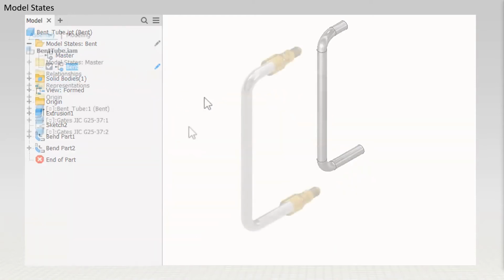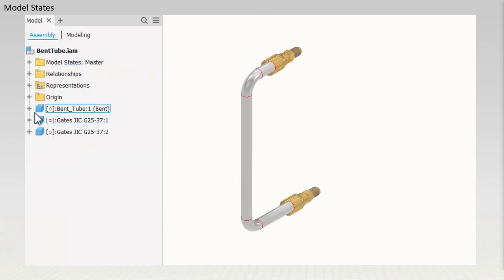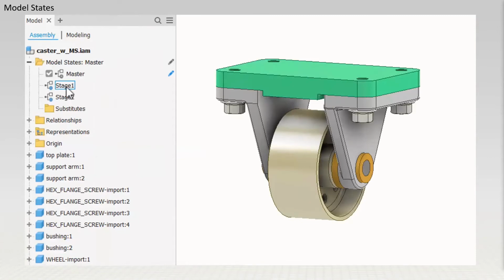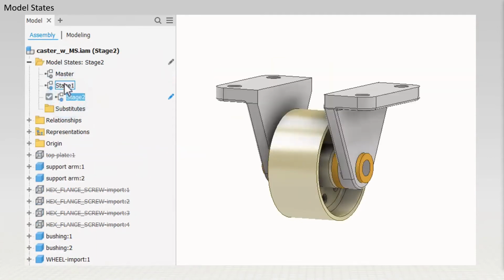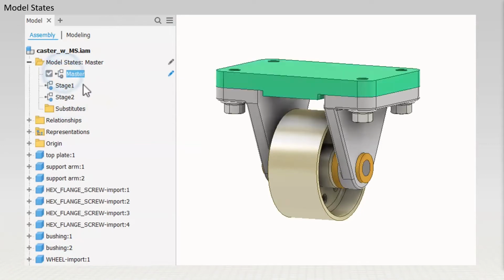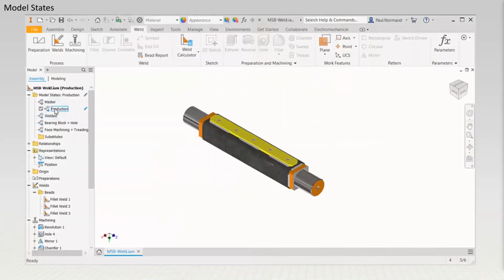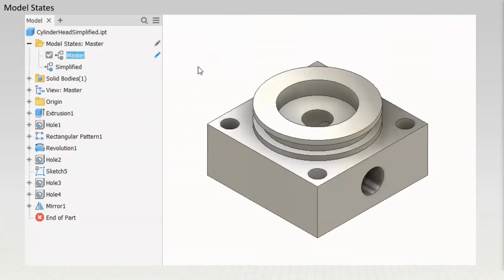As we can see with a couple of these videos here, we're working on parts, and we can work on assemblies. Model states can change components. We suppress or unsuppress different components depending on the job that thing is doing. If it's a part file, we can edit parameters, we can change properties. Basically, we're building the configuration of that thing, that umpteen different types of pin, into one file.